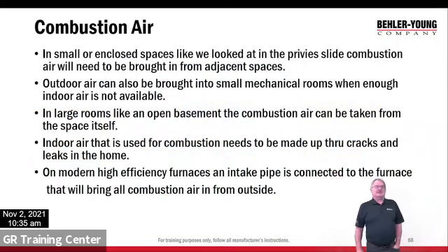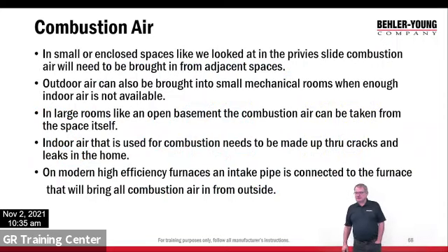Okay, so in a small enclosed space like we looked at in the previous slide, that little 10 by 8 room, 10 by 10 room, we'll need to bring air in from either an adjacent space. So I might have air vents to the basement, providing the basement's large enough, or outdoor air could be brought in. All right, so we're going to bring air in from outside. Okay, so it could be X amount of air outside, and you'll get into homes where you'll see this. There's an air vent coming down next to the furnace. We're bringing air in both at the floor and up at the ceiling. Okay, and there's a requirement for how much that's going to be.